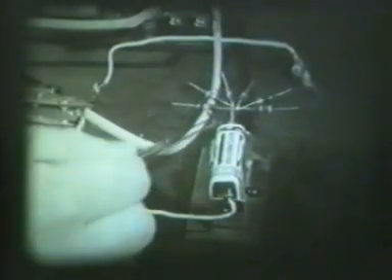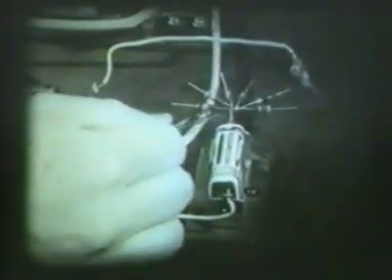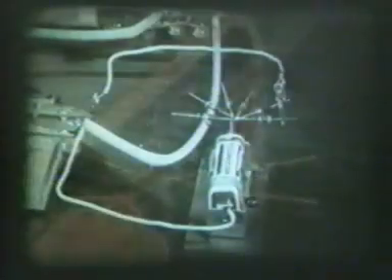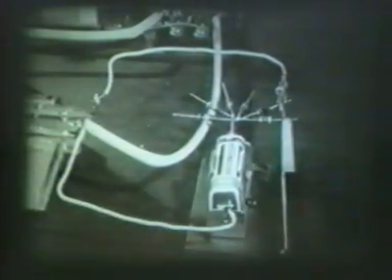The lead from the negative terminal is connected through a resistor to this brass strip, which holds the detector point. The resistor is chosen for best signal-to-noise ratio. This probe will be connected to the vertical input of the oscilloscope to monitor our detector current, and this is the ground.